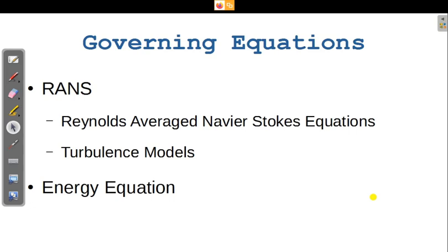In later slides we will see how to understand that. In most applications or software, we will be seeing Reynolds equations. Most flow phenomena are turbulent in nature. That's where we will be using the Reynolds averaged Navier-Stokes equation. It is a slightly advanced version of the basic Navier-Stokes equation which we deal with in basic fluid dynamics. It is like averaging the equation over some time, rearranging, and we get some closure, and then we have additional equations. That's where turbulence models come into the picture. These are the basic governing equations which we can use for solving fluid dynamic problems. If it is a laminar flow problem, we will be solving just the Navier-Stokes equations. Also, whether it is steady state or transient will be based on what kind of terms we include or neglect from the system of equations.